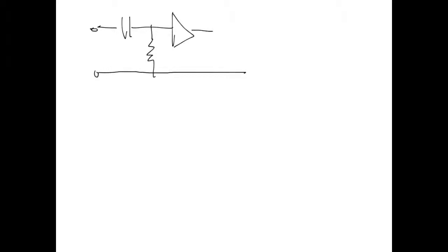So here I just briefly remind you what this circuit is going to look like. First, we're going to have some sort of input here, and I'm going to have a capacitor to an amplifier, and I'm going to have a resistor down to this bar down here, which is frequently ground, and then I'm going to have a resistor here like so with a capacitor. Okay, so this is my circuit here. I have C, R, and then I have RC. So that's my CR-RC circuit.